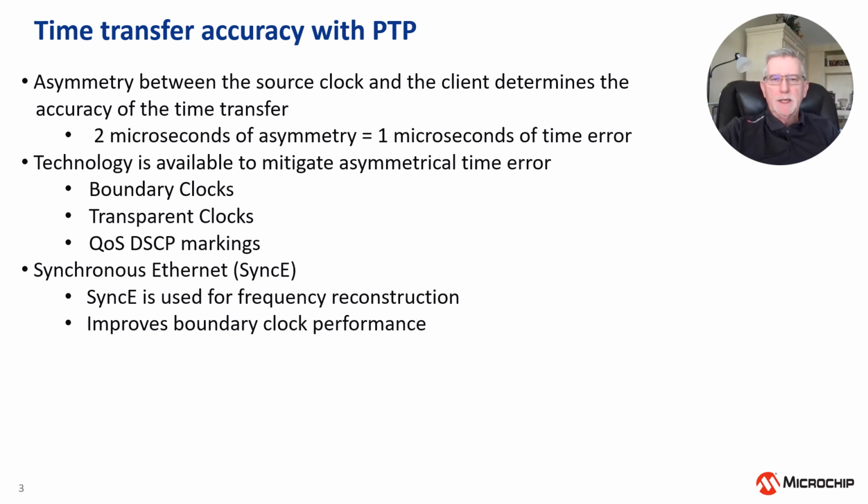The main concept on time transfer is fairly simple. If we have a receiver, for example, that uses GPS as a UTC traceable source, and that receiver tracks 1 microsecond from UTC, we can send a timestamp from that receiver at point A to an endpoint in the network that's consuming the time services at point B. And if the delay of the network is 100 microseconds, we can deliver an accuracy of 101 microseconds to that point B endpoint.